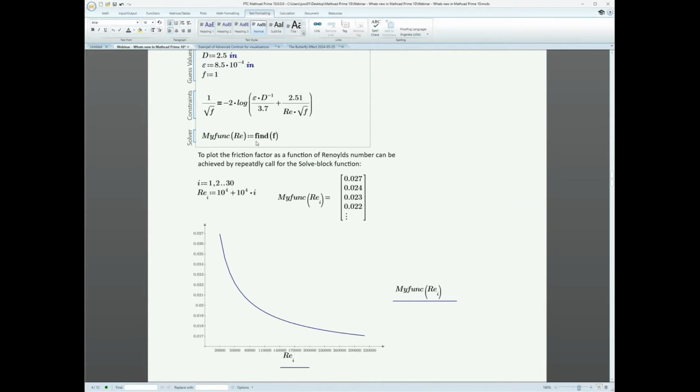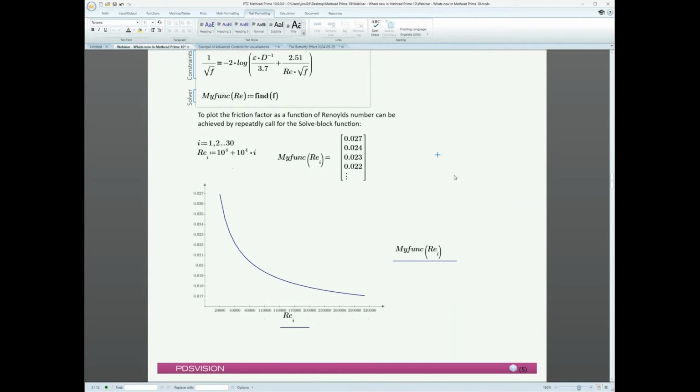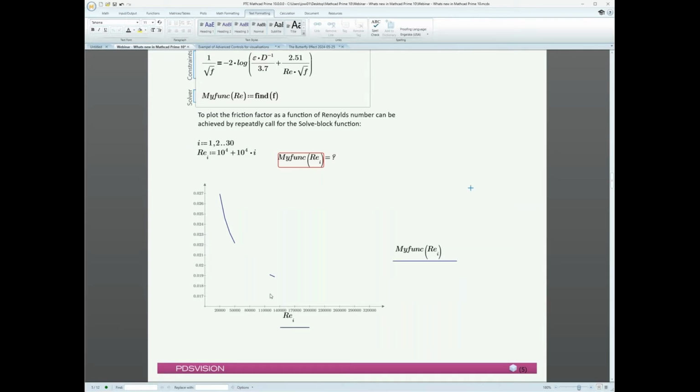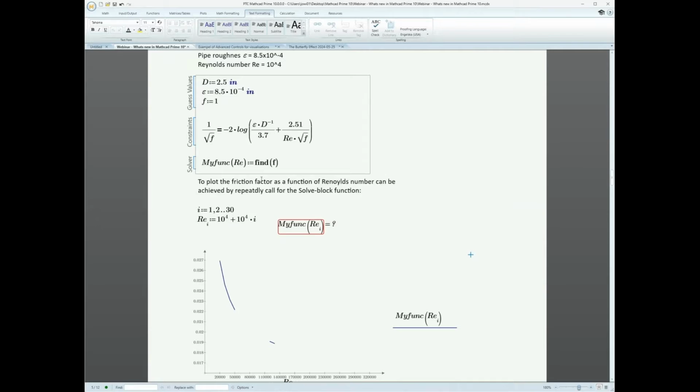So what I wanted to show you just here is if you right click here, you now have the ability to choose which solver you would prefer, or solving algorithm. So auto works mostly fine, but if I take something nonlinear SQP, does that work? Just click outside the boundaries, gives the same result. If I click nonlinear interior point, doesn't work. Well, not to my liking at least. So that's one of the new functions. Auto select is mostly fine.